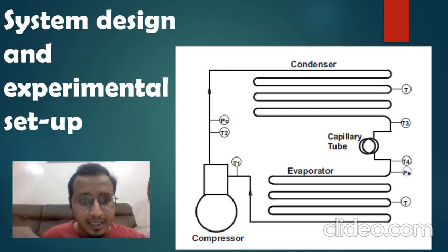An existing split air conditioner was used in the experiments. Consistent with the shape of the condenser, a frame was built and filled up with a cellulose media pad with 5 centimeter thickness and installed in front of the air conditioner. A water circulation system, including a small pump, a tank, and connecting pipes, was assembled to inject water on the top of the media pad. The water circulation rate was constant for all tests. Hot ambient air passes over the evaporative media pad and gets cooled, then passes over the condenser and finally exits from the back side of the condenser.